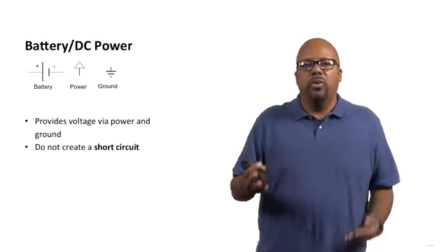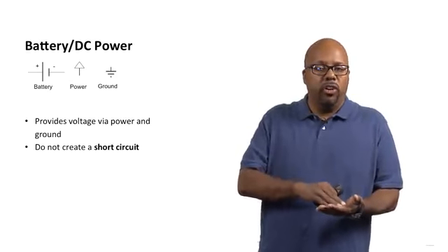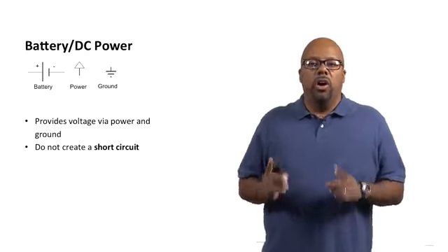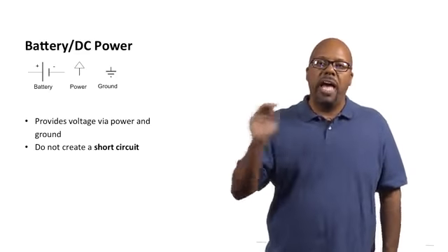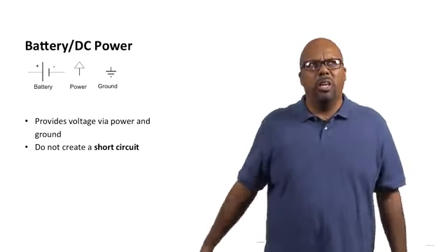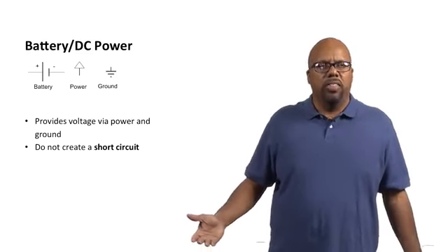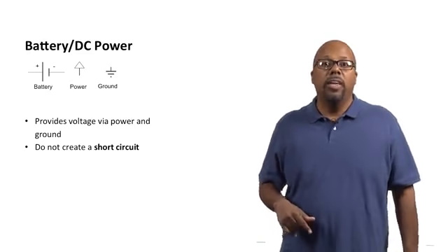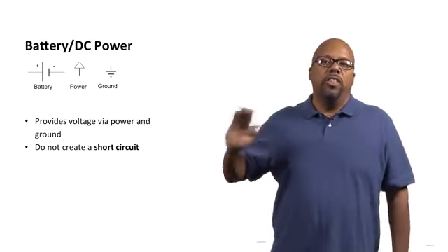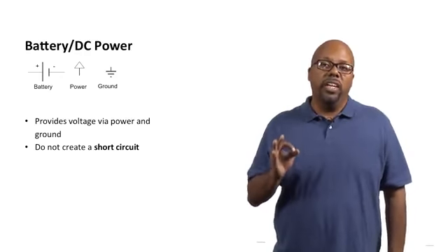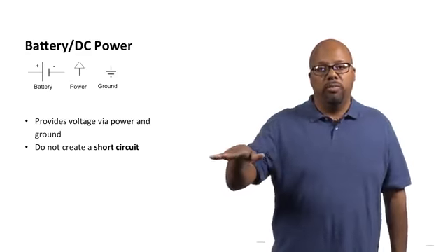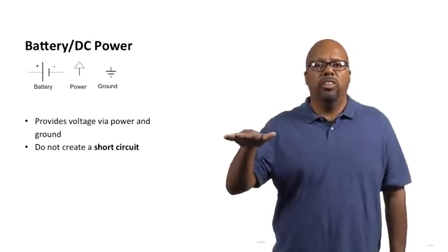To tell you what direct current is, there's direct current versus alternating current. Alternating current is when current goes back and forth. The electrons move back and forth. Like coming out of the wall, I think it's 60 hertz, which means 60 cycles a second. So the current goes back and forth 60 times every second. That's alternating current. Alternating current is good for transmission, meaning it loses less power in long-distance transmission.